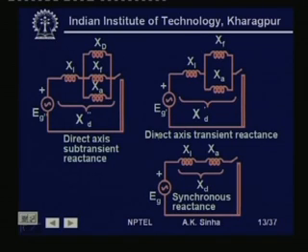So, with a synchronous machine, since we are interested in the maximum current which flows through the machine, most of the time while doing short circuit analysis we consider the subtransient reactance only. If we are considering periods a little after the subtransient period, that is, during the transient period, then we consider the transient reactance. But generally, in finding the short circuit currents, we are more interested in finding the maximum value of the short circuit current. We would be using subtransient reactance only in that case.